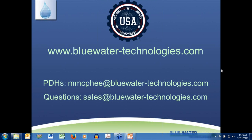There's another question about nitrate and nitrite. So nitrate and nitrite are very simple to remove with a biological process. They're not very cost effective to remove with a purely chemical or physical process, but our biological reactors, and again it can be the same treatment stage, are very effective at nitrate removal. We have many installations across the U.S., across the world, for biological denitrification, and within the industry.